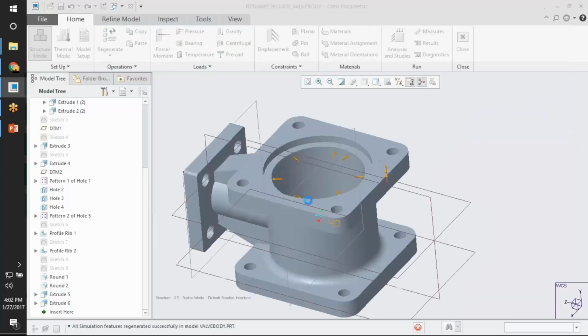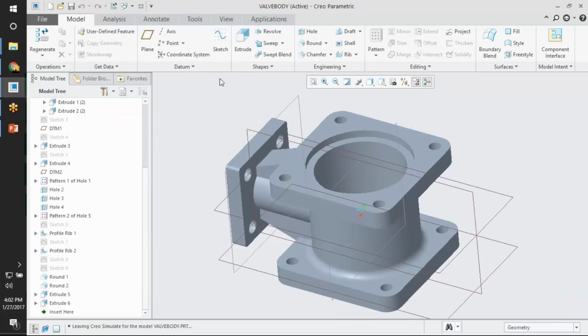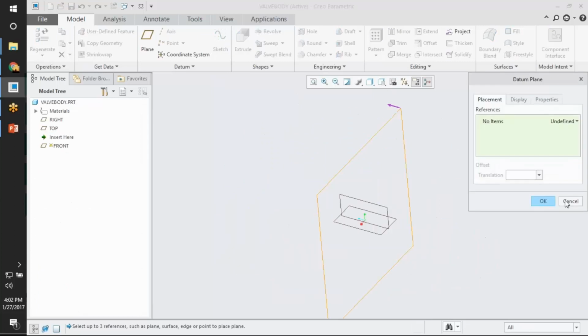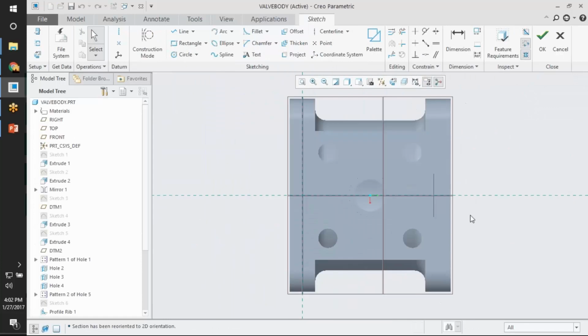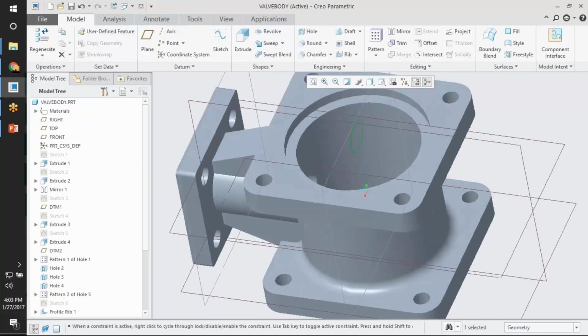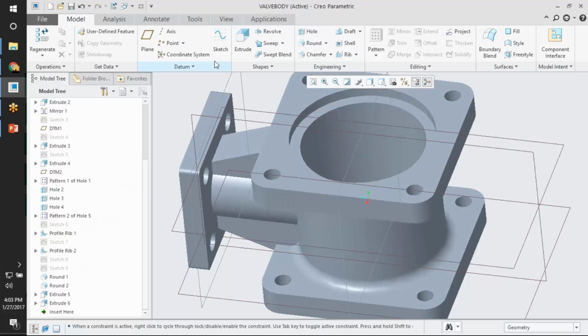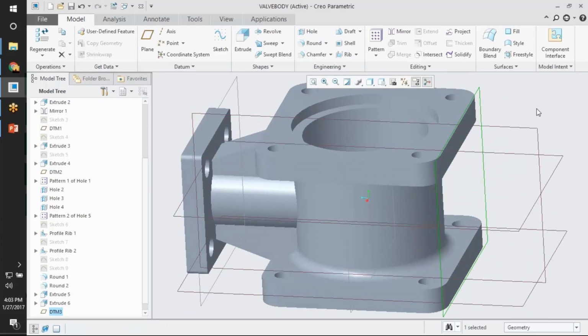So finally I would like to show you how the crack has been inserted. I'm just going to the modeling. I'm just inserting a crack, a sketch, a typical circle. I'm just creating the plane over here. Done.